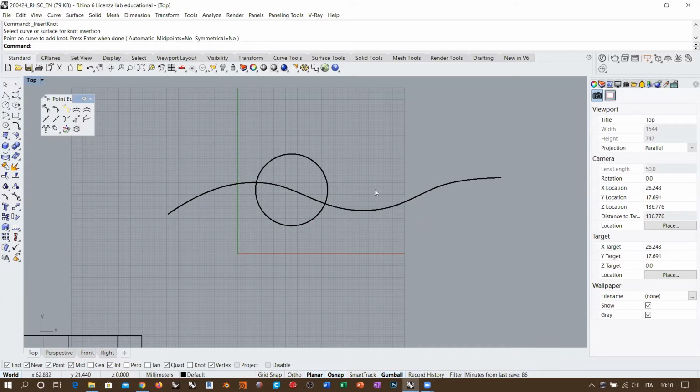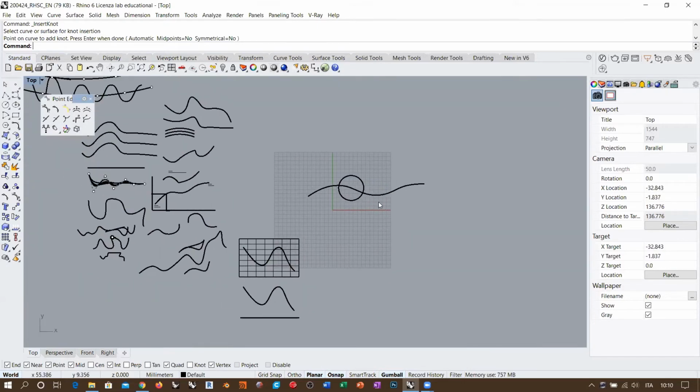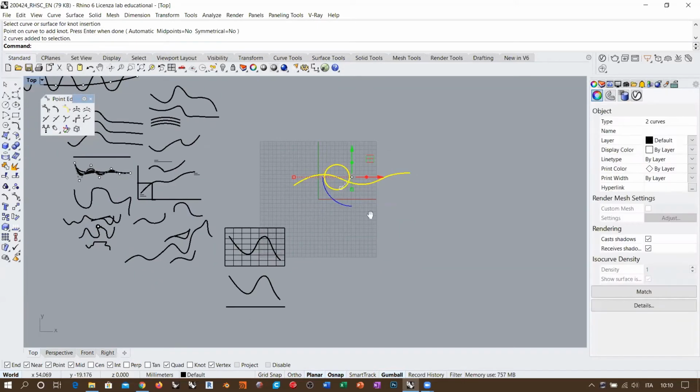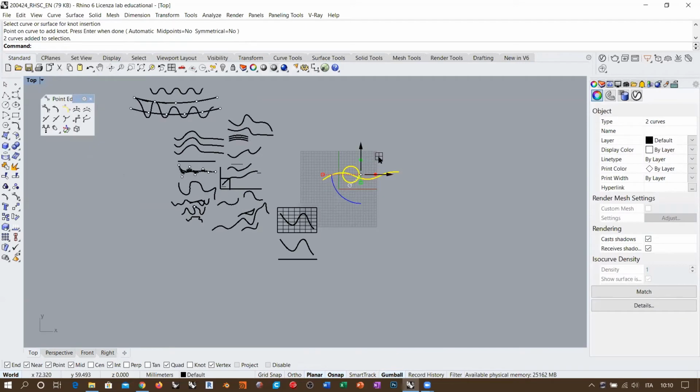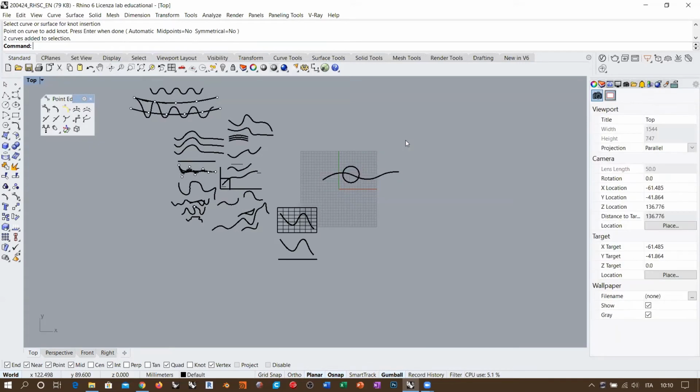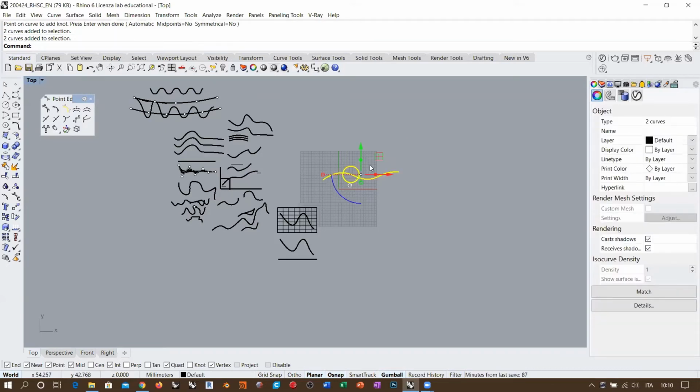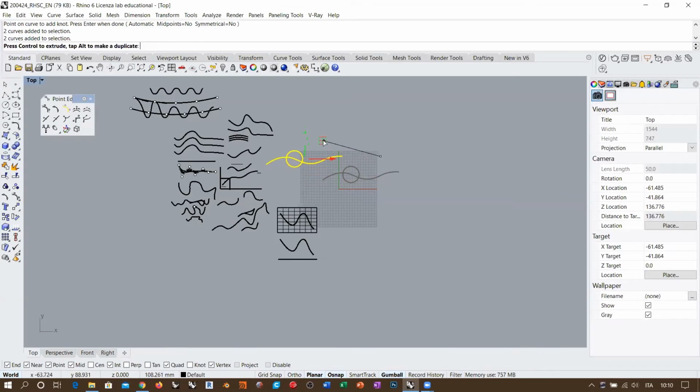Okay, there is one feature that we were anticipating a few minutes ago, which is curve speed. So you always get a uniform knot vector, but you have to deal with the speed of a curve, which is something that also has many consequences, both topological inside when you work inside Rhino, but also in the real world.